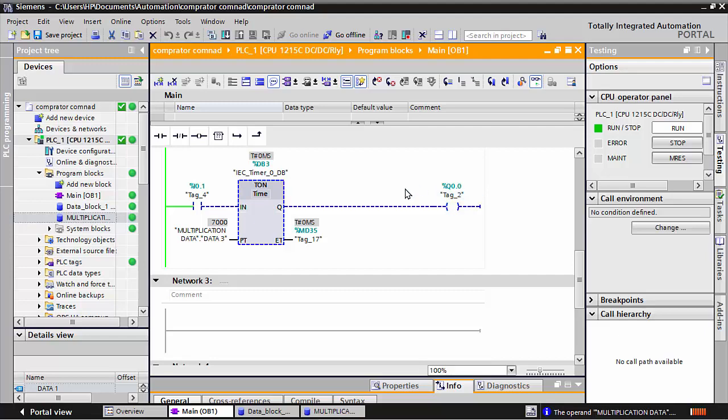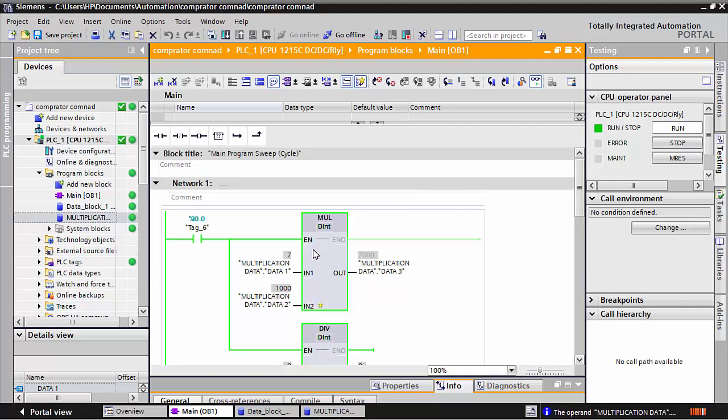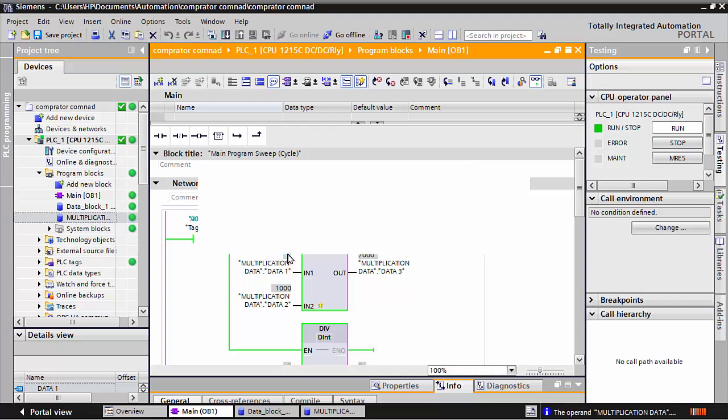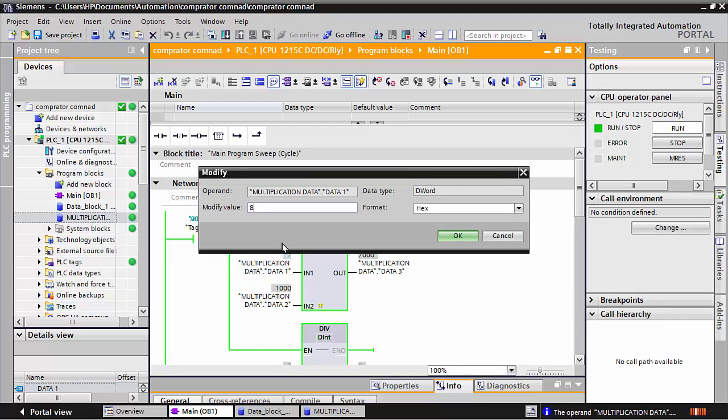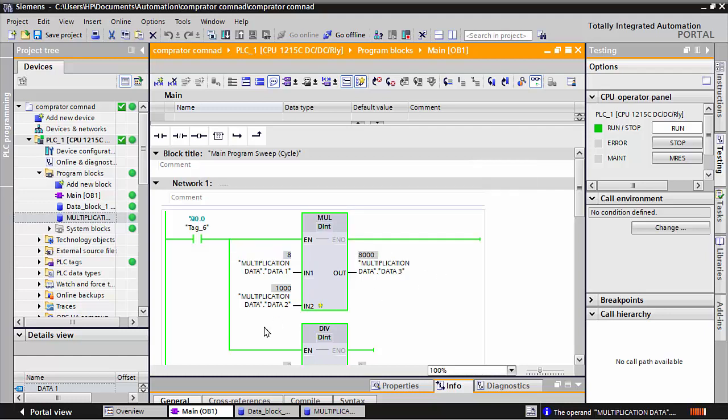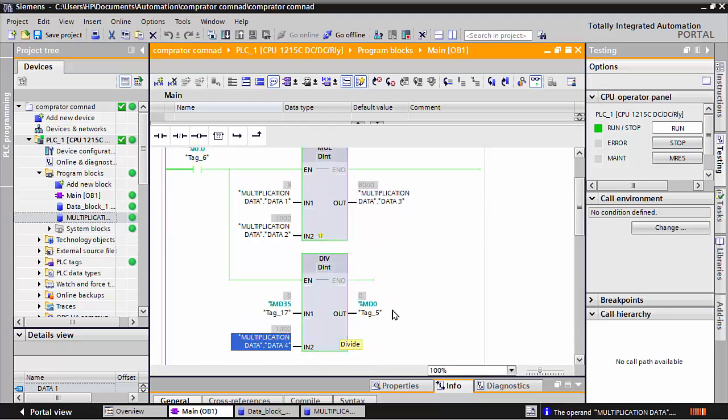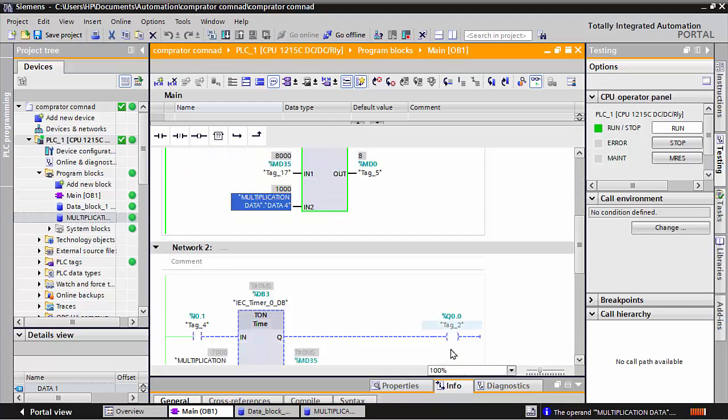And if I like to change this time also, I don't need to go anywhere, I only change it here, put 8, and then you will get 8 seconds, yani make the execution on, and you can see here also the running time 4, 5, 6, 7, 8 and after 8 seconds your output will be on.